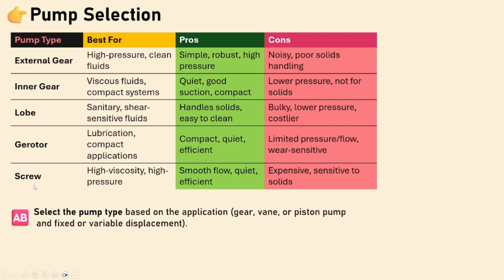Screw pumps are great for high viscosity and high pressure applications. They're smooth, they're quiet, and they're efficient. However, they are very expensive and very sensitive to solids. Right? So the actual type of our pump is going to be based on the application.